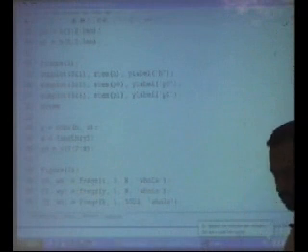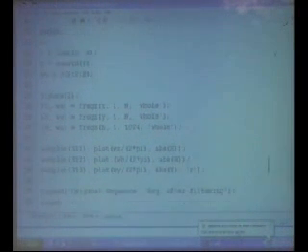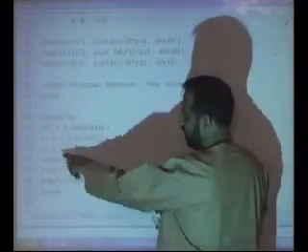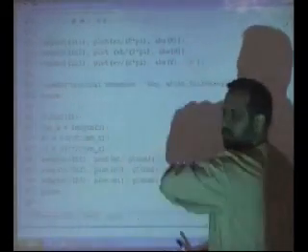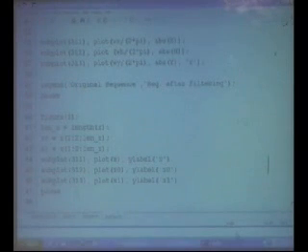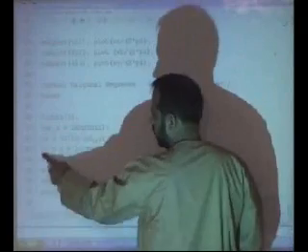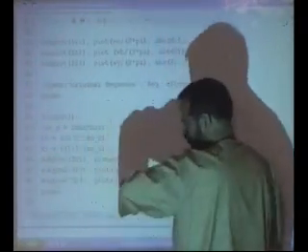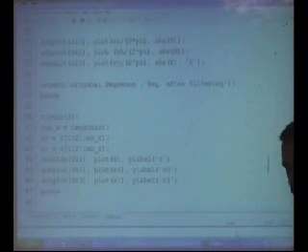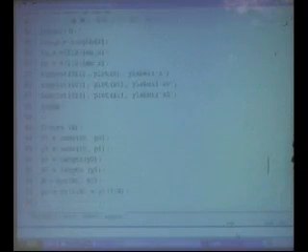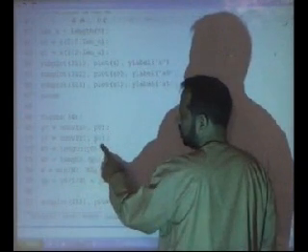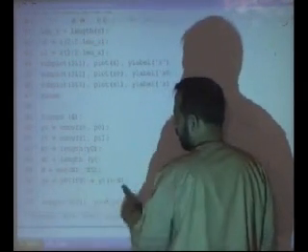The second is that you ask MATLAB to do it differently. These are all plots here. This is the switch. You give the first sample to x0, then x1, and so on, so you split the input into two parts. This is the switch, 0, 1, 2, 3, 4, 5, 6, 7. So you split it into two streams, x0 and x1. The first sample goes down and the second sample goes up. You split the inputs into two, and then what you do? Pass them through both filters: x0 through P0, x1 through P1, and then add them together.